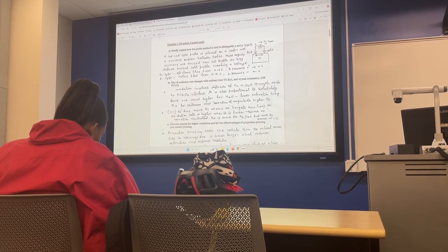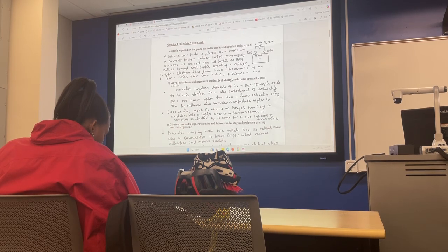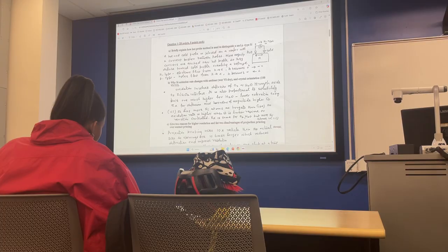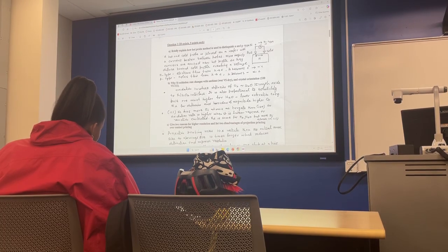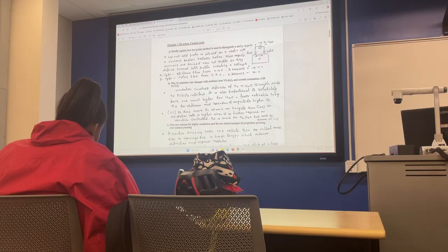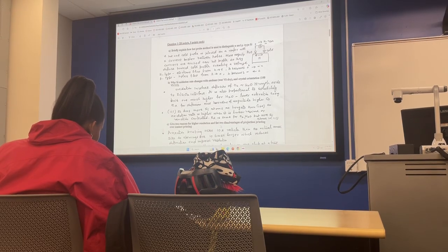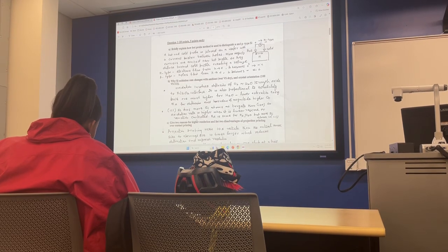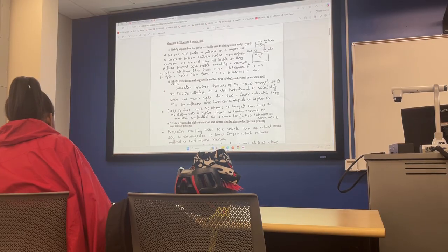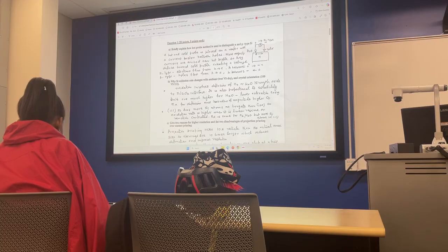And then what happens when you switch the orientation? Orientation 111 has more atoms per centimeter square. It has higher atomic density, so you have more targets of silicon when oxygen or H2O is coming. So you got more targets, meaning you're making much more SiO2. So the oxidation rate is higher when you use 111 versus 100. So that was the answer for that one, right? It has more targets, and therefore it's faster oxidation, and therefore the rate is higher for 111 over 100.